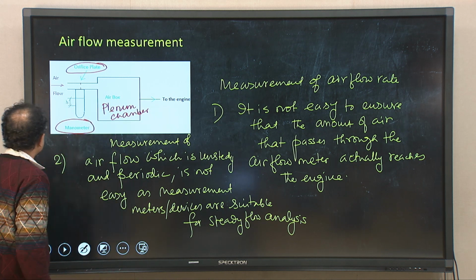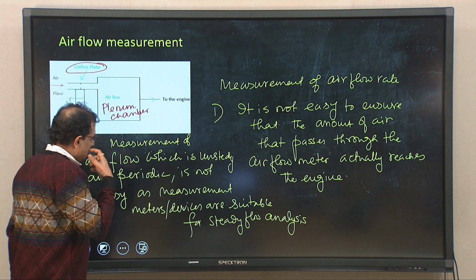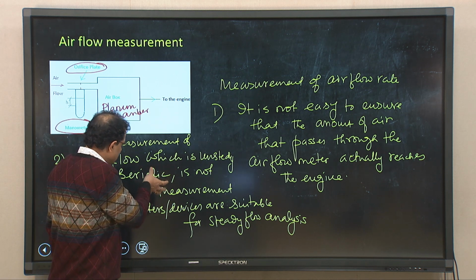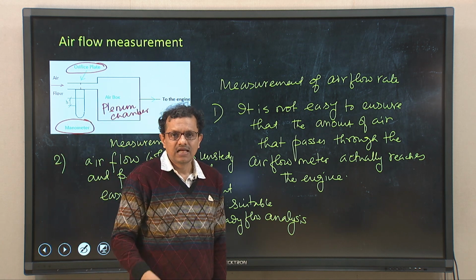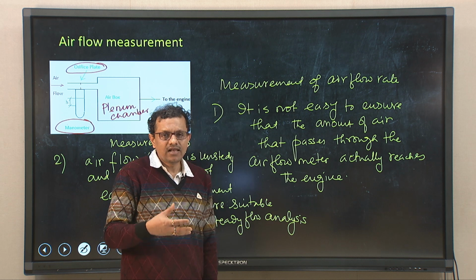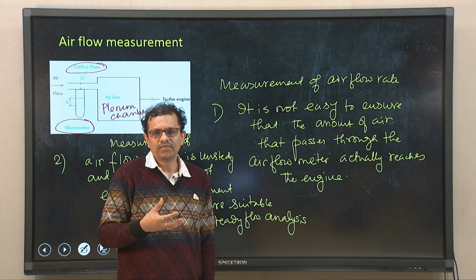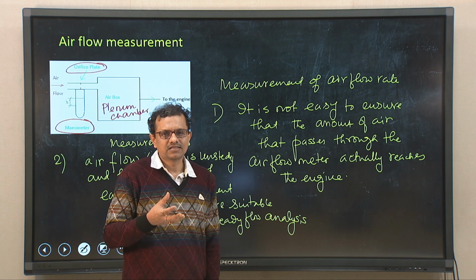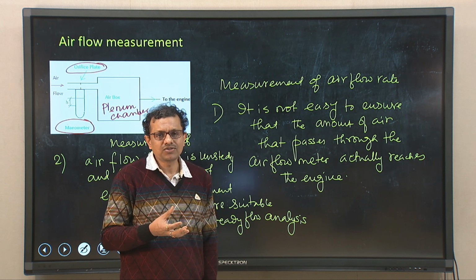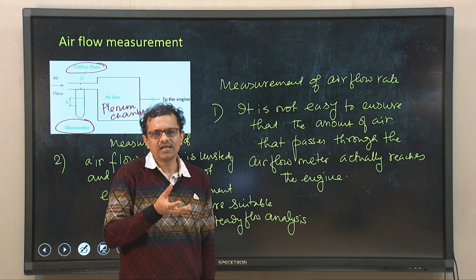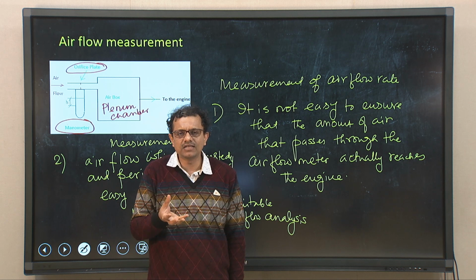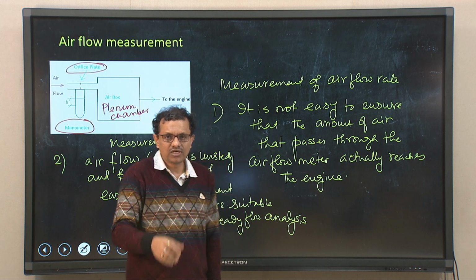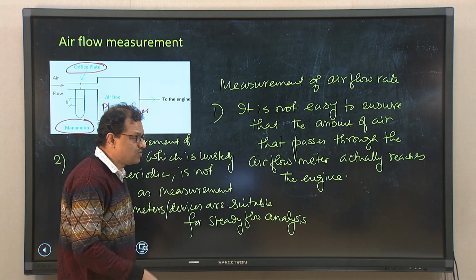So, the problem associated with the unsteadiness or periodic nature of flow can be alleviated if it is a multi-cylinder engine, but even then some degree of unsteadiness will be there, and also air has low viscosity. So, the air drawn into the engine cylinder will have some frequency, or it will resonate with the engine frequency. If that is the case, then the actual measurement will be affected.